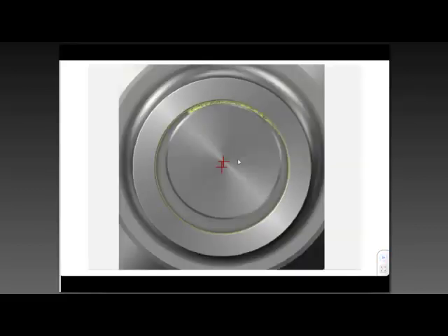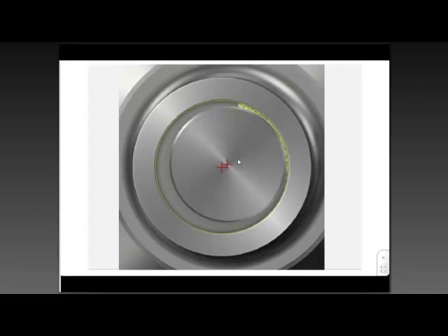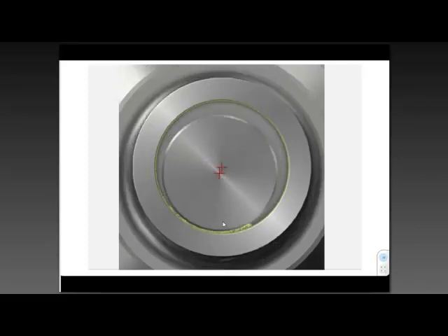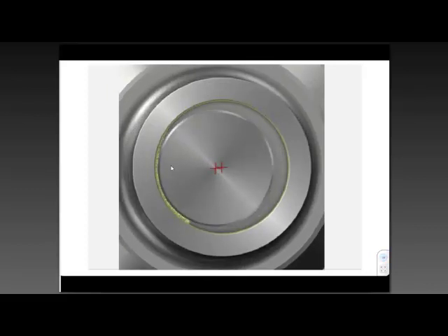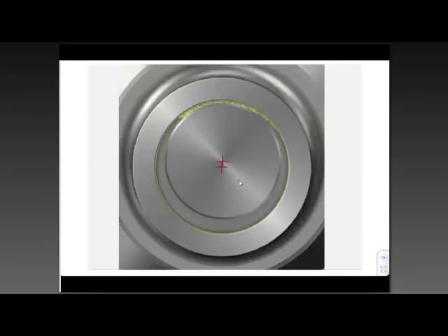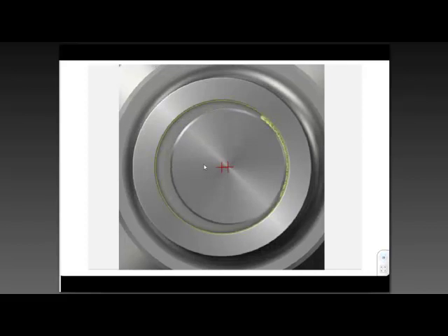This is a very bad situation. We've got oil whirl. The shaft is actually tracing around the bearing. We've sort of established a wedge of oil, but it's moving at the full radius of the bearing. And you know, if we had our prox probes on there, we would see exactly what's going on. And there's lots of other fault conditions. Normally, it should just move in a small motion sitting on that oil wedge.